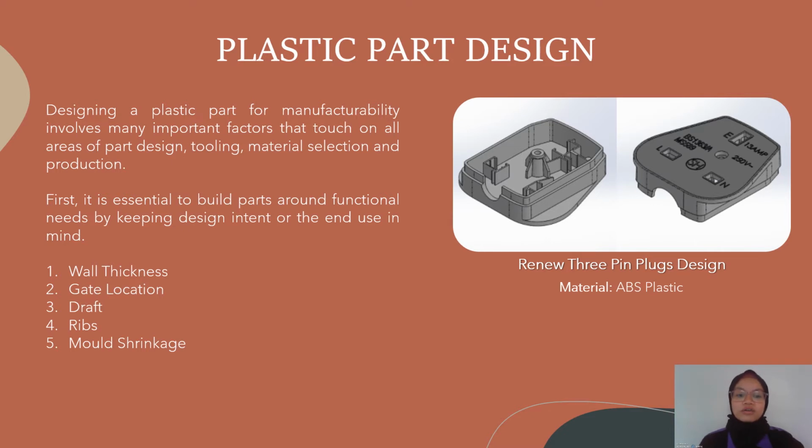Here are a few ways to avoid molding shrinkage issues: adjust the formulation, adjust the mold design to the dimension you want based on the expected shrinkage that will occur, and optimize the processing parameters such as mold temperature, melt temperature, injection speed, pressure, time, or cooling time.